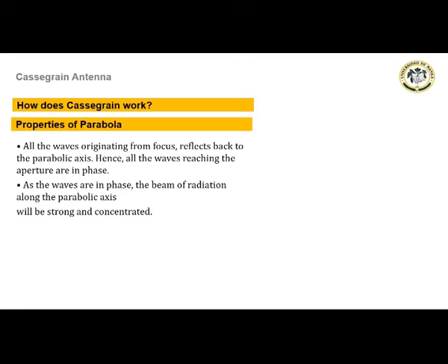Properties of parabola. All the waves originating from the focus reflect back to the parabolic axis. Hence, all the waves reaching the aperture are in phase. As the waves are in phase, the beam of radiation along the parabolic axis will be strong and concentrated.